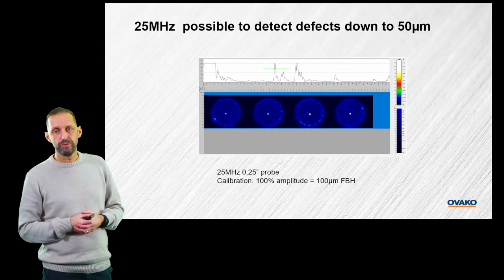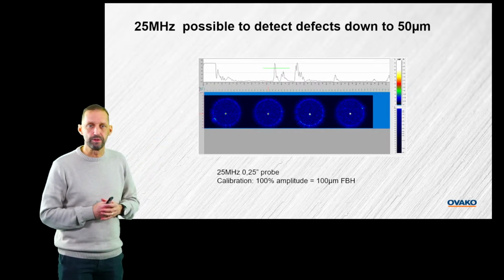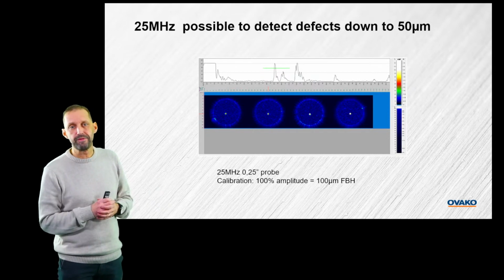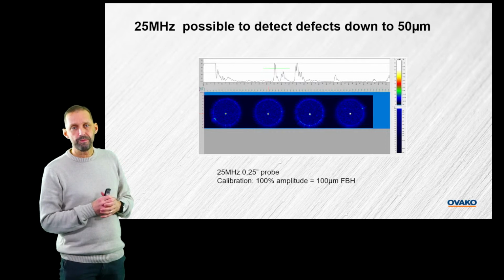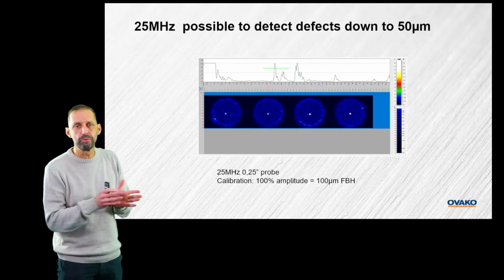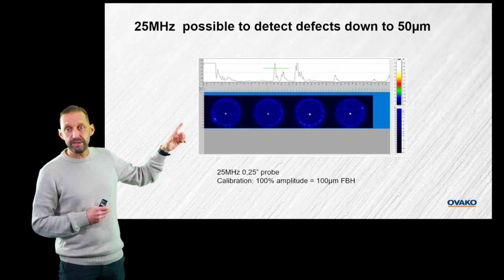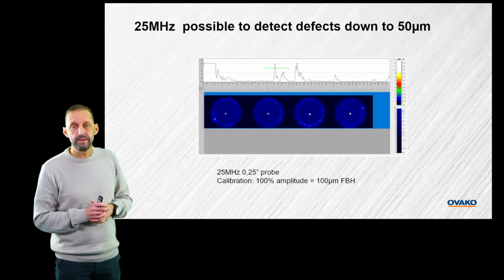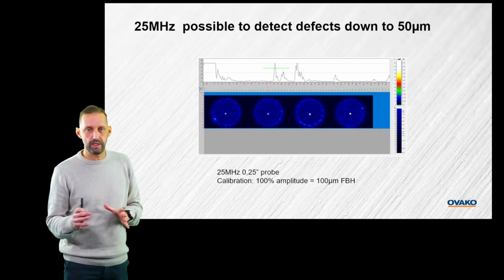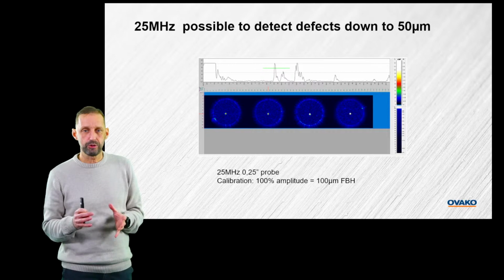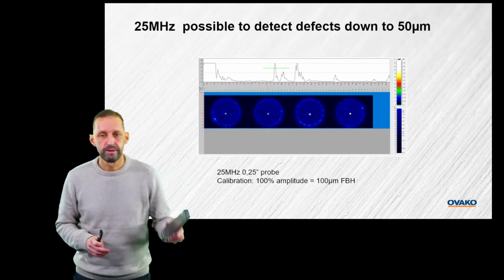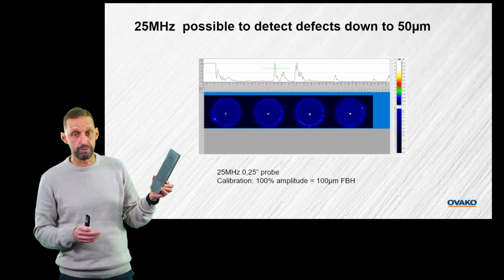And you can see here, the picture is actually a C-scan, they call it. We call it. It's actually one piece with a perfect defect in it, and what you see is all the layers of the volume stacked in. So you see actually volume then compressed to an area, and you can see that defect, the smallest defect you see here is 50 microns. So if it's a perfect reflector, we can see down to 50 microns, which is quite good, and then you start to get that. And you remember that volume is huge in comparison.